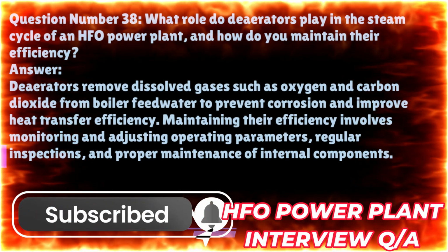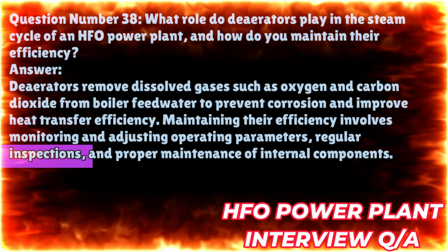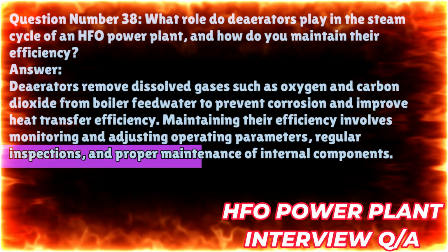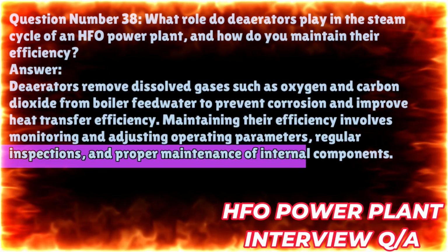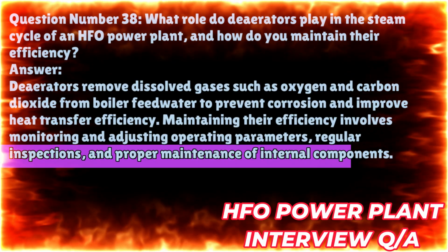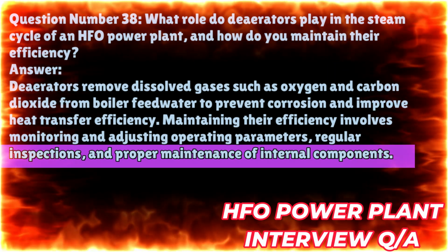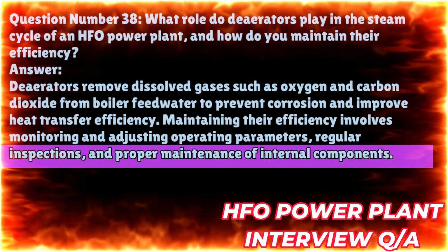Question number 38. What role do deaerators play in the steam cycle of an HFO power plant, and how do you maintain their efficiency? Answer. Deaerators remove dissolved gases such as oxygen and carbon dioxide from boiler feed water to prevent corrosion and improve heat transfer efficiency. Maintaining their efficiency involves monitoring and adjusting operating parameters, regular inspections, and proper maintenance of internal components.